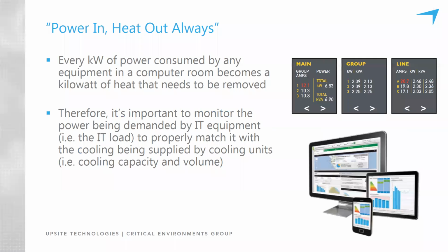We recently published an article in Mission Critical where we quoted Ken Brill, one of the founders of the Uptime Institute, who said, when it comes to data center cooling, it's as simple as power in, heat out, always. In other words, every kilowatt of power consumed in a computer room becomes a kilowatt of heat that needs to be removed from the computer room and ultimately the building. This includes all the power conversion and distribution losses, as well as every kilowatt of electricity consumed by the IT